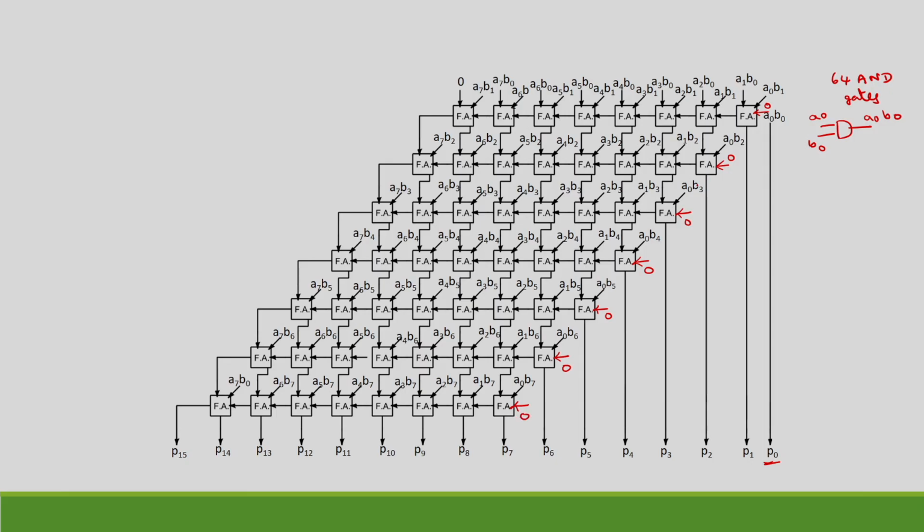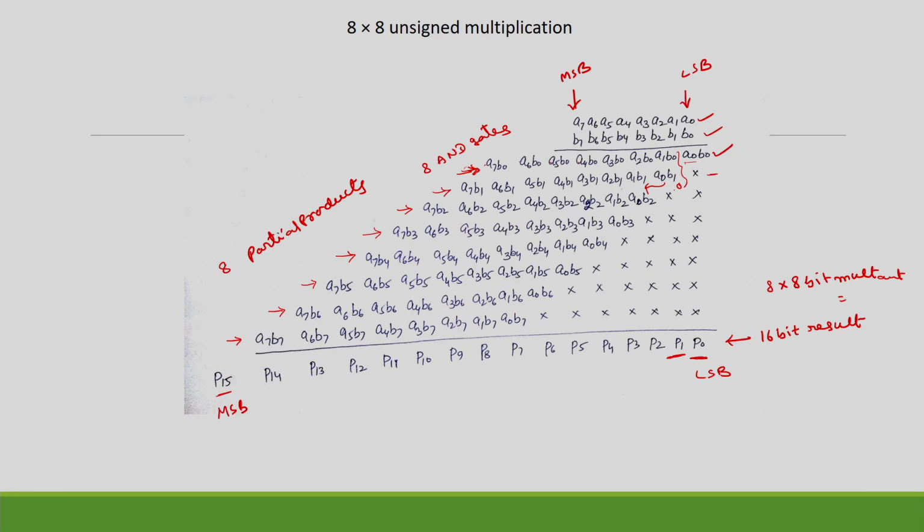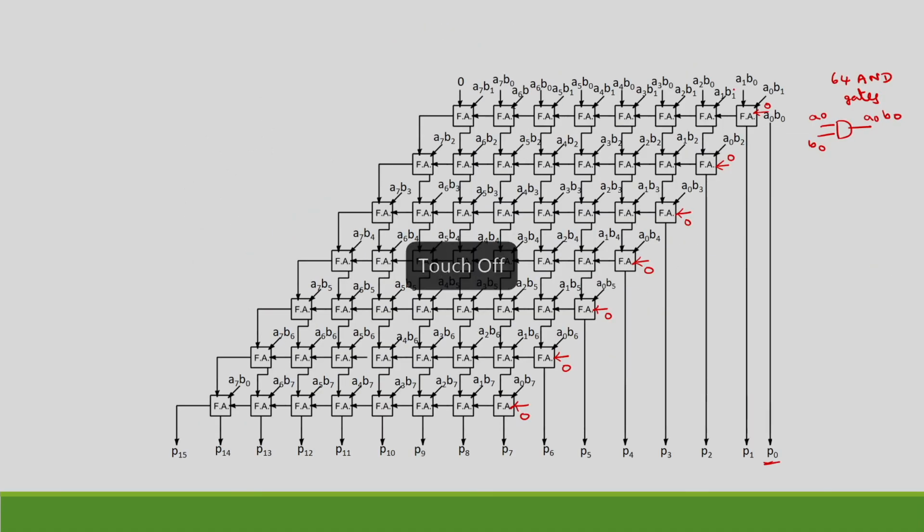In fact, for this half adders are enough, but to have uniformity, because we can instantiate full adders, I am implementing the entire algorithm using only full adders. So, that is why the third bit I make as zeros. We can see here this A1 B0 plus A0 B1.